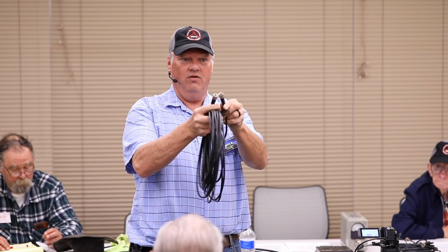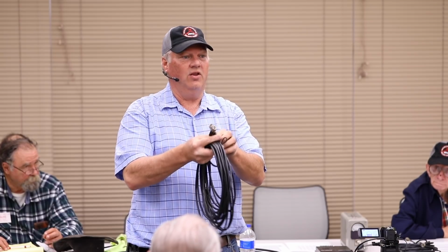The experiment is set up as follows. You put a power into it. You note what that power is. I'm going to ask somebody to write that down, okay? We're all going to look at the meter and say, what's the power going into it? And then we're going to unplug it from our test unit, and we're going to insert this cable. The test unit is from the output port of the radio, that little flexible coax in the back of your radio. I have a double male connector, which emulates the double male connectors here with no wire between it, okay? So the loss is virtually, for our experiment, zero.